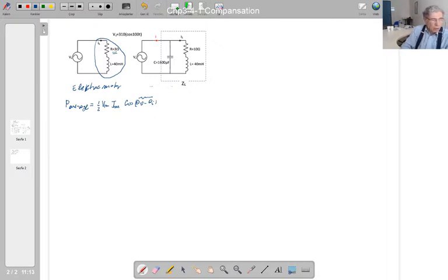should be what? In our calculation, we are going to say it is going to be different from 0. Since this is different from 0, cos of the phase difference is going to get a value. So we are not going to get the maximum average power. So how are we going to arrange that? We are going to calculate this, and then we are going to calculate Q, which is the reactive power, equal to 1/2 Vm Im sin(theta V minus theta I).